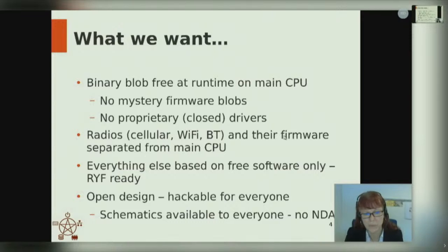What we also wanted to achieve to be as free as possible is that we want this whole thing to be as blob-free as possible, especially concerning the main CPU at runtime, because there are a lot more CPUs inside of that system running, for example, the modems and a lot of other parts. We don't want to have some mystery firmware blobs inside of that, and we also, of course, do not want any proprietary closed source drivers or closed source libraries inside the user space of the main CPU. So no blobs as much as possible.